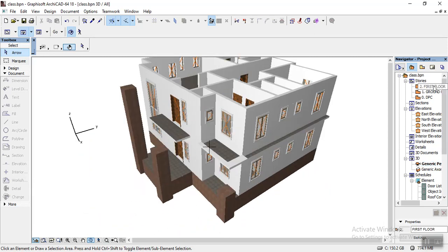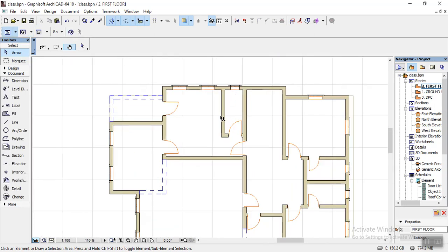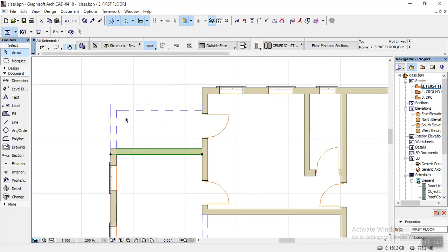So let's edit the first floor. First of all, there is no other floor coming in, so we have to change most of the walls to 150mm, being internal walls. So what I need to do now is move this backward because I don't need this design here anymore. I'll move this backward, then I'll expand this wall to this.